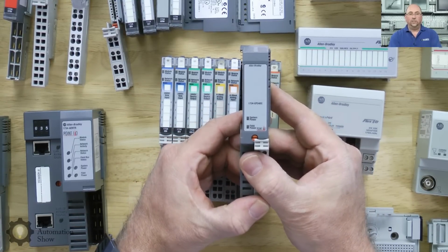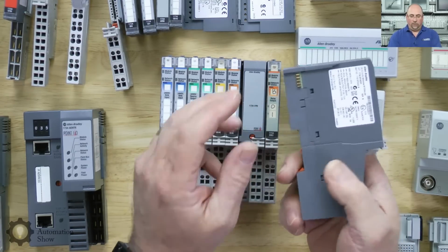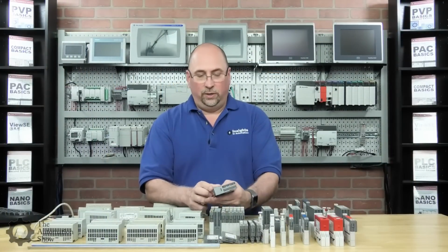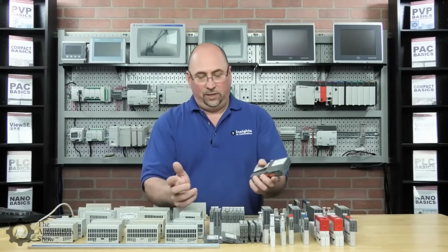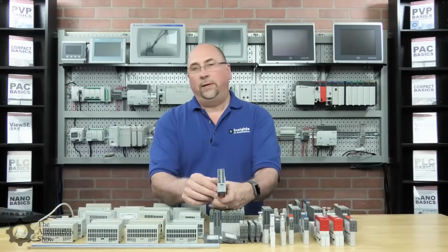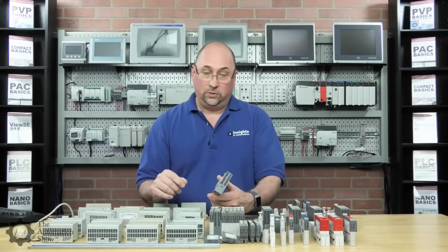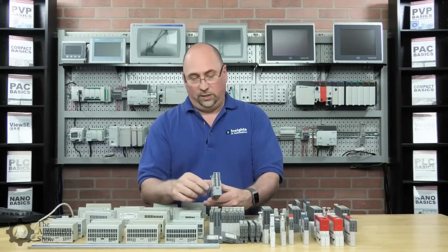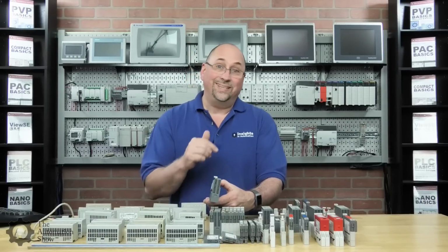EP24DC. What this allows me to do is add more module power to the backplane. So it breaks the power bus. It also supplements the module power so that you can provide more power to your modules. Depending on which modules, typically it's 12 or 13 modules, and then you'll need one of these EP24DCs. But some modules draw a lot more current. So again, probably best to use IAB. We have a video on that on the channel here and an article over at the automation blog on it, as well as using the new Ethernet IP configuration tool that's inside of IAB now.